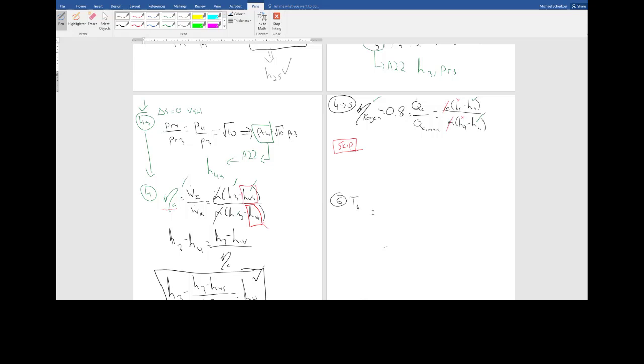So here T6 is known, and P6 is equal to, because it's only pressure, right? So this is equal to P4, which is equal to P5, which is equal to 1,000 kPa, right? Because we took 100 and multiplied by root 10 twice.